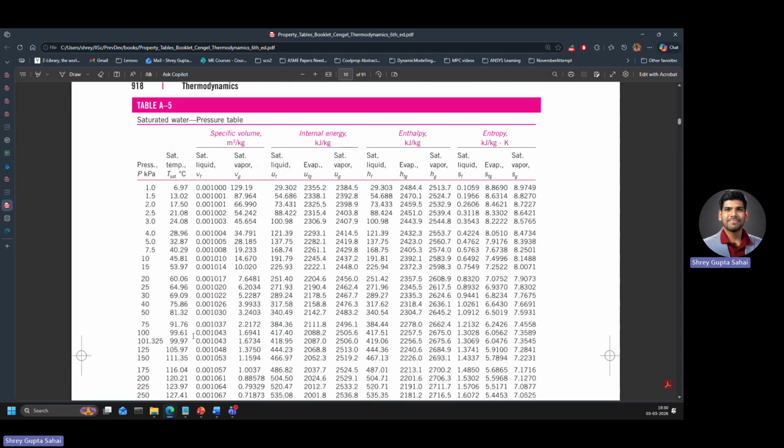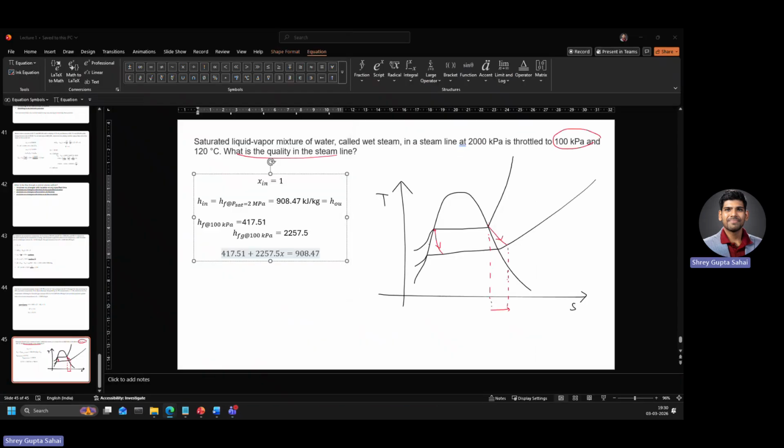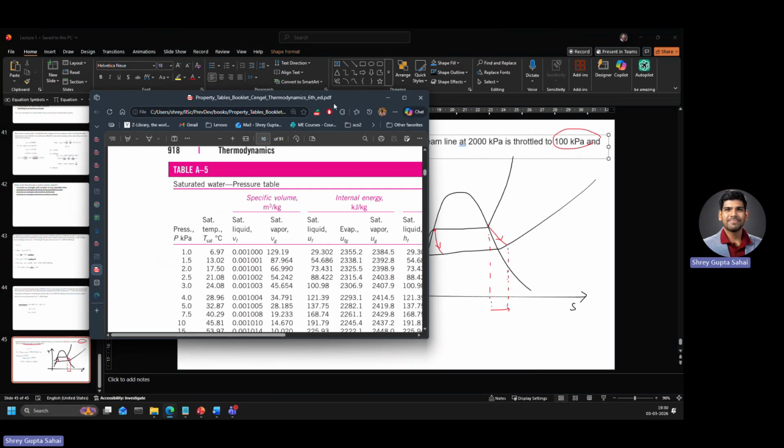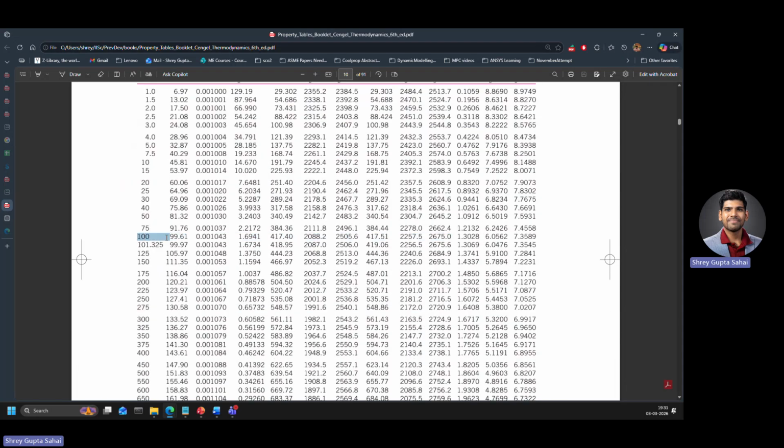But at 100 kilopascals, HG is very high. Let me see if I'm making some mistake somewhere. It's throttled to 100 kilopascals and 120 degrees Celsius. That is also an important clue. I didn't check that. See, at 100 kilopascals, the saturation temperature has to be 99.61. If it is higher, okay, wait, I think...